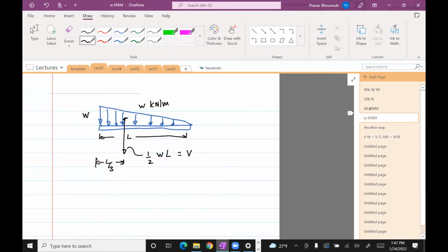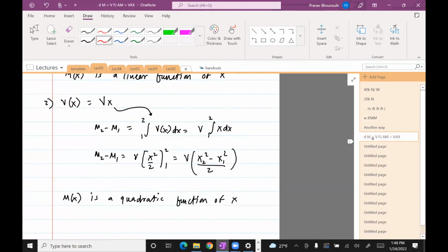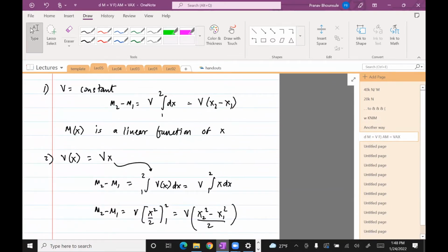Can we see it here, which is, so when we had constant for v, it became a line on the moment equation. When it was a line with a linear function of x like this, it became quadratic. Okay, if you go down one more problem where we did that, you'll see the same thing is true. So what I'll do next time is I'll use this equation, this logic to resolve that problem, and hopefully that is much simpler than what we've done so far.